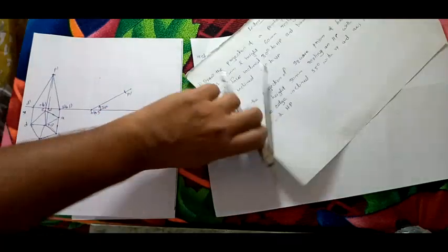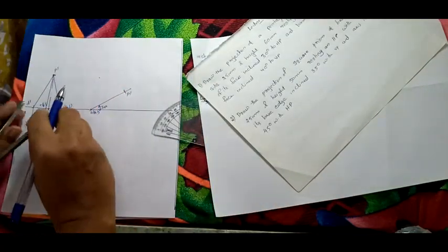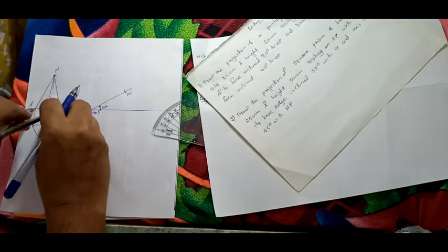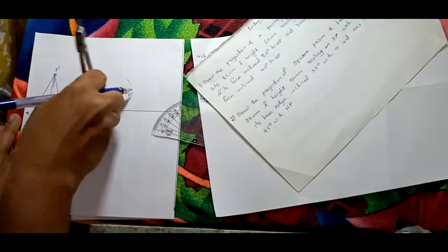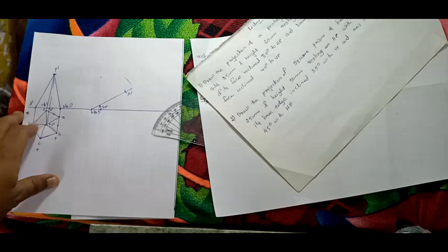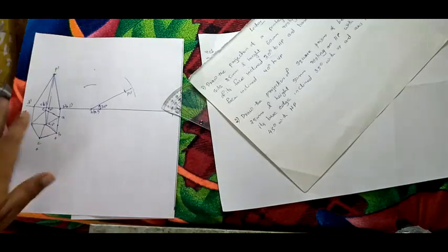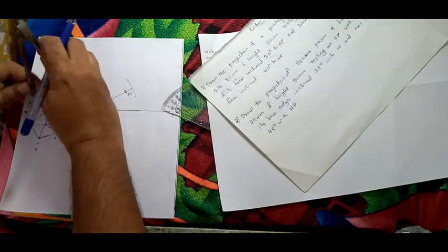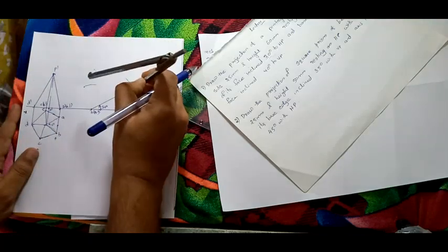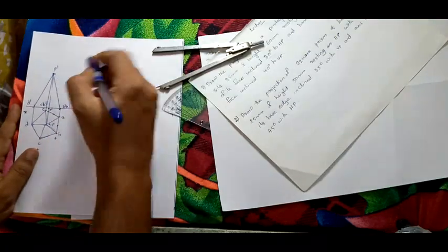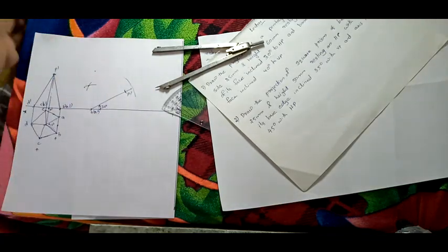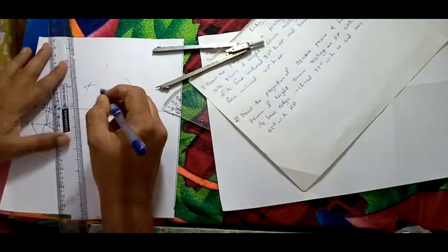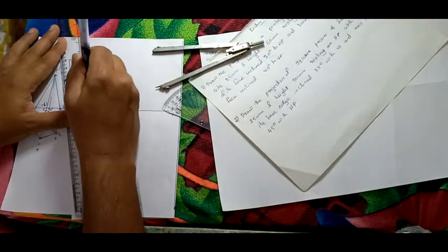Now what will we do? Now we have to complete this triangle, right? First we will complete this triangle: take this distance, that is the B dash to D dash distance, and cut an arc like this. See, cut an arc like this. This should be light. Next I will take the P dash to D dash distance, so from P dash cut an arc like this. This will touch here. How to draw a triangle, you already know. The same principle we are drawing here. So join here.